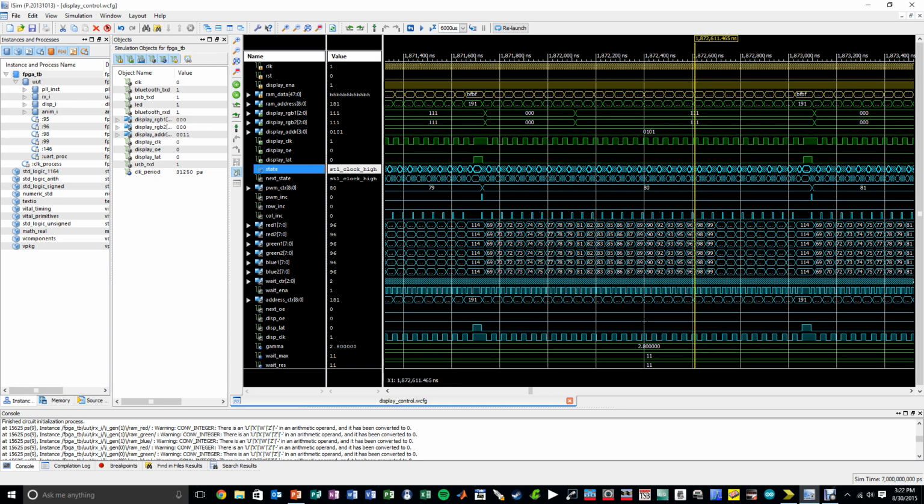But what we've done right now is that I have connected the FPGA board directly to the oscilloscope, so we can do this measurement very quickly, so that you can indeed see that the logic behavior from all the IOs going out of the FPGA into the RGB matrix is exactly like the FPGA simulation predicts. So let's take a step out of the computer and take a look at the setup and the logic analyzer that's running on the oscilloscope, and take a look at the waveforms.